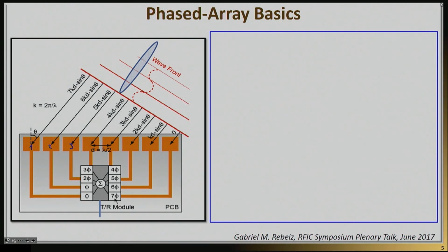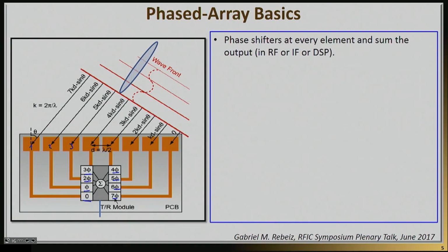If you put these antennas together and control the phase you're feeding them with, you can coherently add the signals they're getting back. It's that simple of an idea. When you coherently add the signals, you gain a very sharp beam width, much sharper than each antenna would give you by itself. So you need to include phase shifters, shown schematically here, that control the phase of each antenna element. That's true for both transmit and receive.